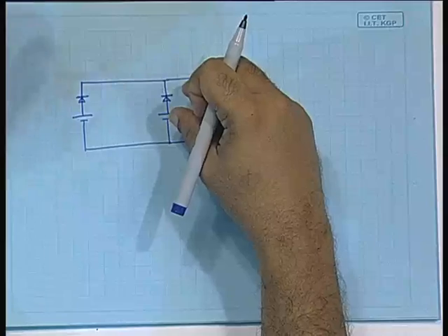The same thing is done in case of photovoltaic panels. This is just one diode provided for the whole panel, because the panels are to be connected in parallel. Individual cells are never connected in parallel, because you need a larger voltage. So, individual cells are always connected in series. When there is a question of connection in parallel, this diode is mostly provided. For example, earlier in the 80s, many Indian manufacturers did manufacture panels without this diode, but nowadays the ones that are coming mostly have the diodes built in.